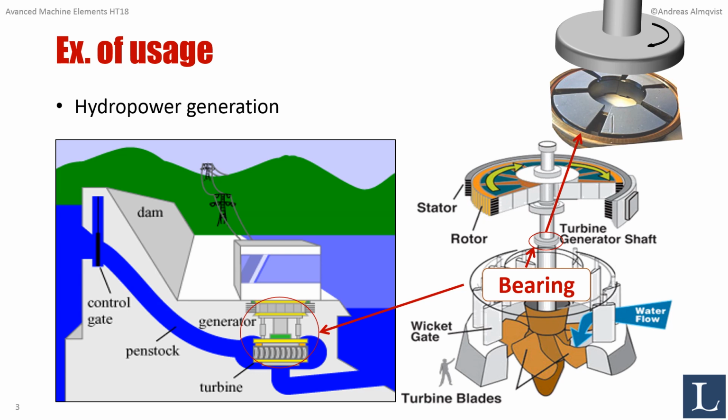And this is what it typically looks like. So this is the series of pads. Okay, in this case it's only 6. Typically in this application they are about 10 to 20, 30 pads, and the size of them is like half a meter times half a meter. So these pads, they can rotate freely on a pivot, either a line pivot or a point pivot.